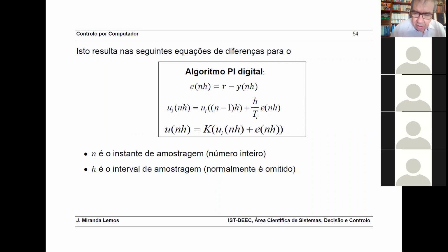You cannot go too far. I mean, if you have a high order system, of order say 4 or 5, and this is quite common, you can find combinations of poles and zeros such that if you use a PI controller, no matter how brave you are in selecting K and TI, you are not able even to stabilize it.